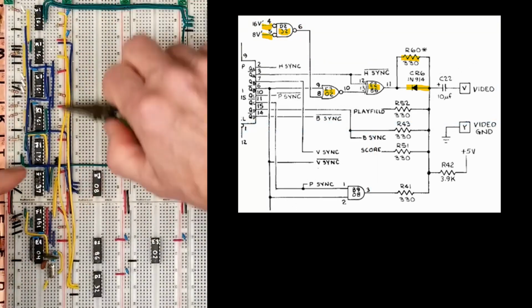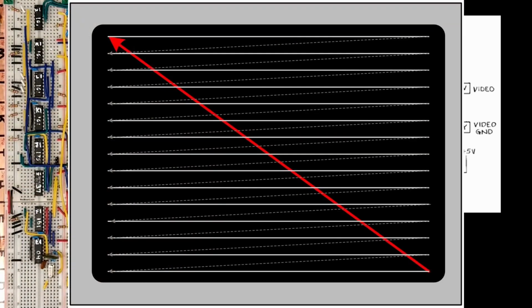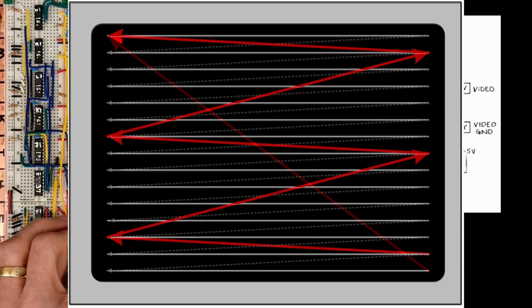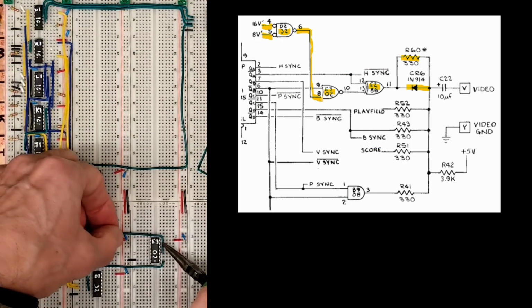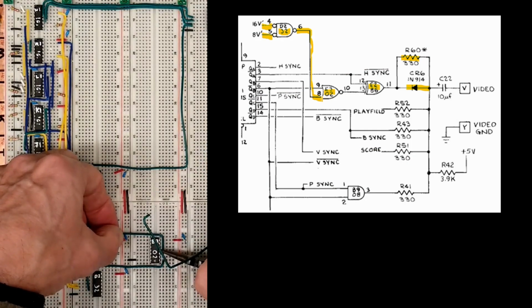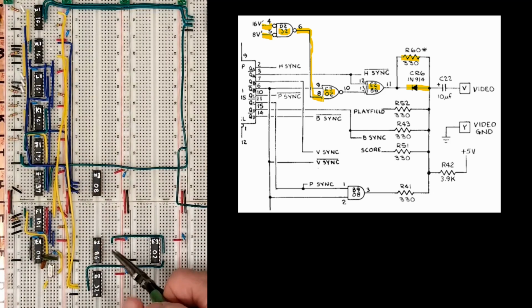Vertical retrace is not some magical super fast return to the top as shown in many diagrams, but takes some time. There are still horizontal retraces happening during the vertical return, as you can see here. Another thing to discuss at this point is that there are no pixels in a CRT. There are lines, but there are no pixels.